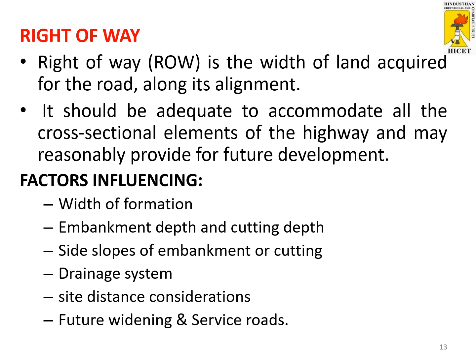These factors influence the land acquisition process. They are the width of formation, the embankment depth and the cutting depth, side slope of embankment or cutting, drainage system, site clearance considerations, future widening, and service roads. Depending on these factors, we have to acquire the land for future development.